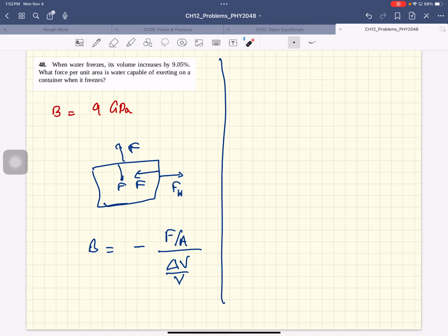A disc between vertebrae in the spine is subjected to a shearing force of 600 newtons. 600 newtons is your weight. Okay. Find its shear deformation using the shear modulus of that. The disc is equivalent to a solid cylinder, 0.7 centimeters high and 4 centimeters in diameter. So 4 centimeters, that much. Okay, so that's how big your disc is.